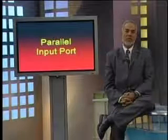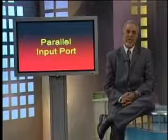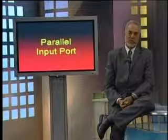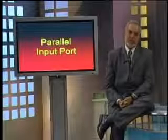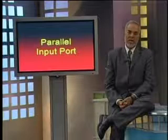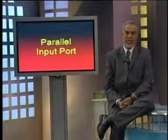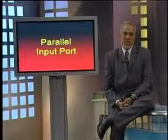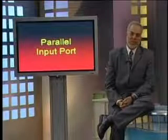Depending upon whether we want any combination of 1 and 0, we just pass this data from the 16 switches to the data bus through the tri-state buffers. These tri-state buffers would be enabled if and only if our address is correct, and secondly, the IO read is activated on the control bus. In this example, we used 7E as the address to which we have mapped the input device.